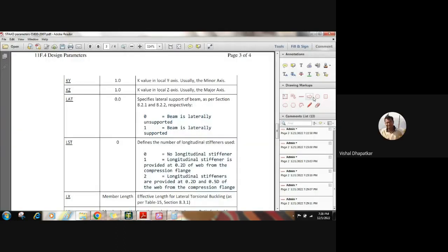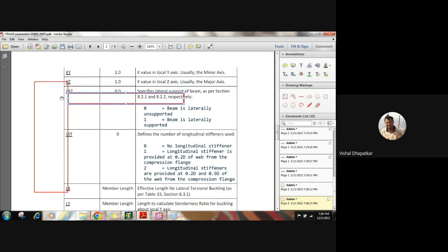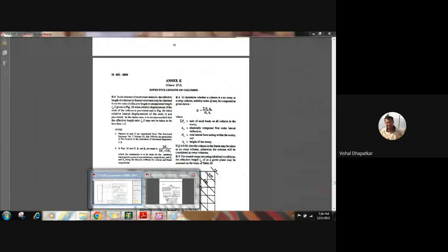No sir. It will not give, right. If my column is big like this, and in front of it my beam is only this small, there is no use of this beam, so this will not provide a restraint because its column stiffness is much higher than this beam stiffness, right? So if this deflects, this will not resist, and it will not support it at all. So in that case what will happen, the total building will sway, right?